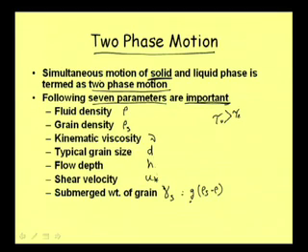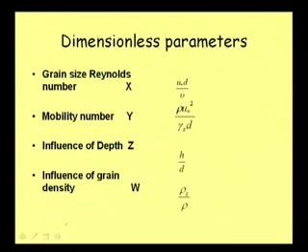So in this part, if we carry out dimensional analysis, as these are the influencing parameters, if we take repeating variables as say rho and depth, the typical grain size d, and u star, then by dimensional analysis we can see that the interaction of these parameters can be grouped into some non-dimensional terms, and these non-dimensional terms are influencing the flow.